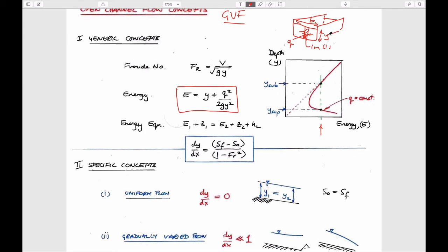So if you know what the energy of the flow is between an upstream point and a downstream point, then you can use this to, if you conserve, if there are no losses within the system and it's horizontal, say, then this would be a straight line. And you could calculate what the energy was at the upstream. And if you put a constriction in this and still have the same flow velocity, you would be able to get a subcritical flow, which is everything above this line here.